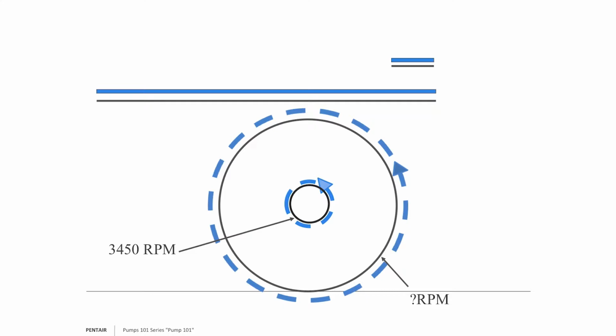But here's the thing, remember it's a solid object, correct? I told you the cast iron impeller is solid. It spins 3450 RPM in the center. It spins 3450 RPM on the outer peripheral. Because there's a greater radius, you see that there's more velocity. The impeller imparts velocity onto the pump, onto the water. Okay? This velocity is what then becomes pressure and head down the road as we go through the pump. If you listen to my Pump 101 lecture, we've talked about this in greater detail.